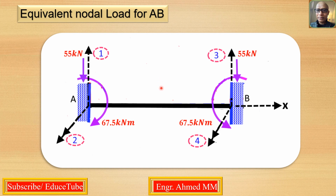Same forces, same value, equal in magnitude, but we have to put them here in opposite directions. If you compare with the previous slide, you will see this one showing clockwise, but in the previous slide it was anti-clockwise. This one showing anti-clockwise, but in the previous slide it was clockwise. So equivalent nodal loads for AB.